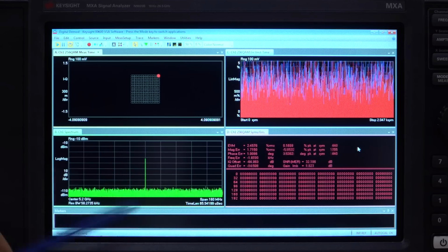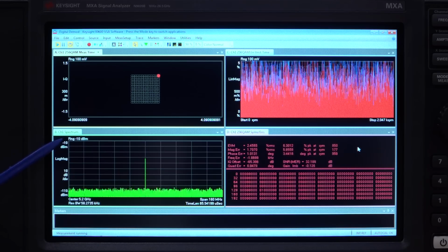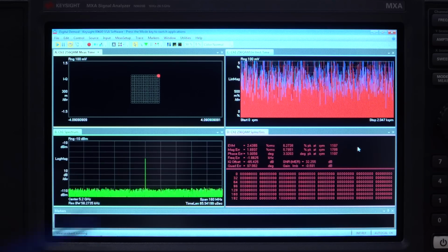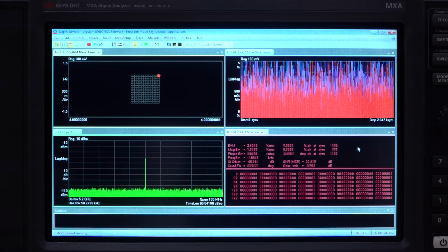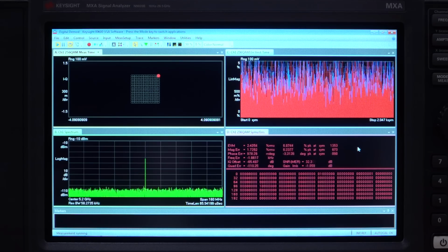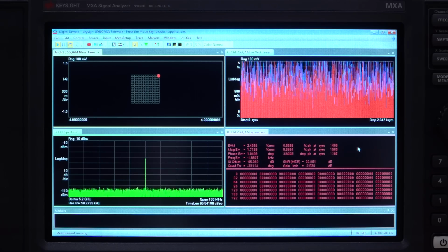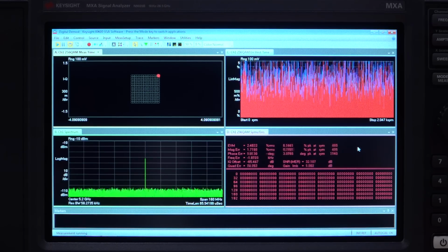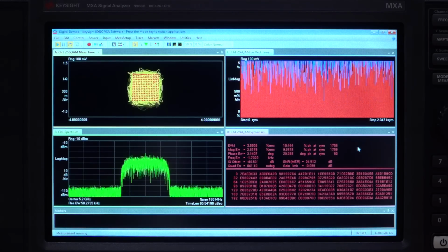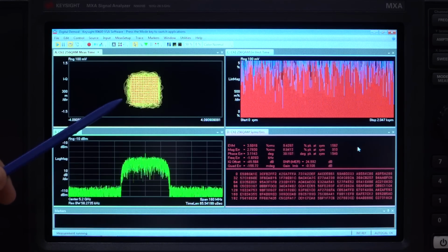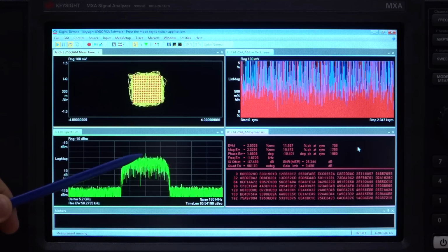So having said that, as you can see, we have quite a bit of signal coming out. So this LO is at, the reference here is minus 10. So minus 10, 20, 30, about minus 30 dBm is coming out of the mixer, and I'm applying about 10 dBm to it. So there is quite a bit of LO leakage. Now normally this is not a problem, there are ways to get rid of it, but we're just leaving it alone and see what happens when I apply the IQ signal. So I'm going to apply the QAM constellation, and here is our QAM constellation, and you can see that the instrument often catches the QAM, it loses the lock and it catches it again. It sees too much LO feed through. In fact, the LO feed through is now even larger.